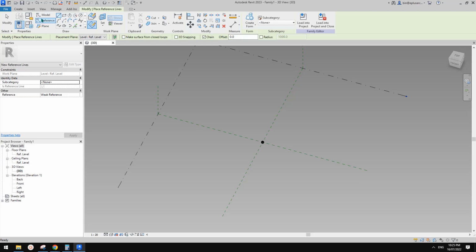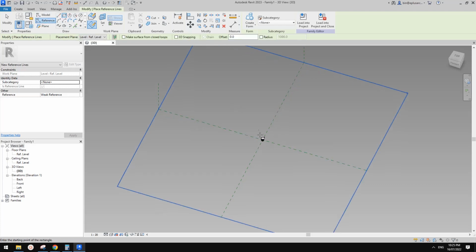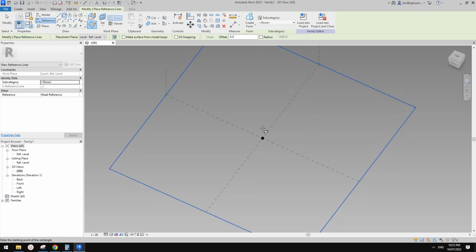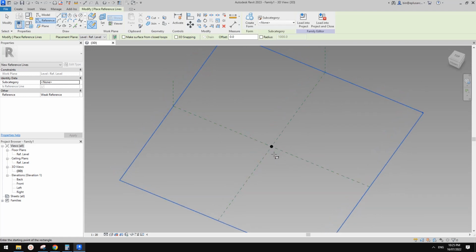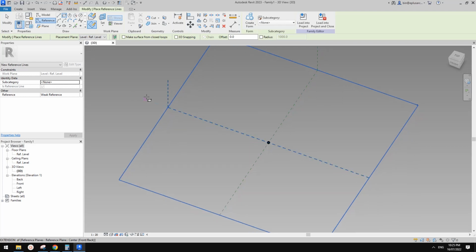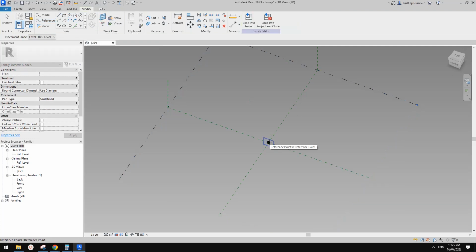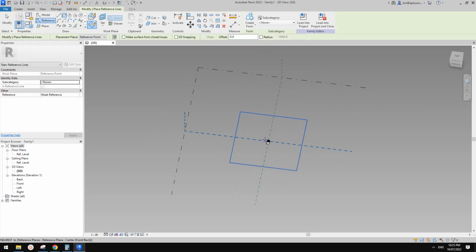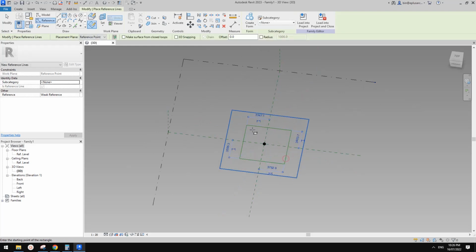First, reference. There are different ways you can draw all these reference lines onto levels as well, so the method I'm going to show you is not the only one. So: reference rectangle, draw on work plane, set work plane, pick the work plane of this point, and then I'll do this reference line.